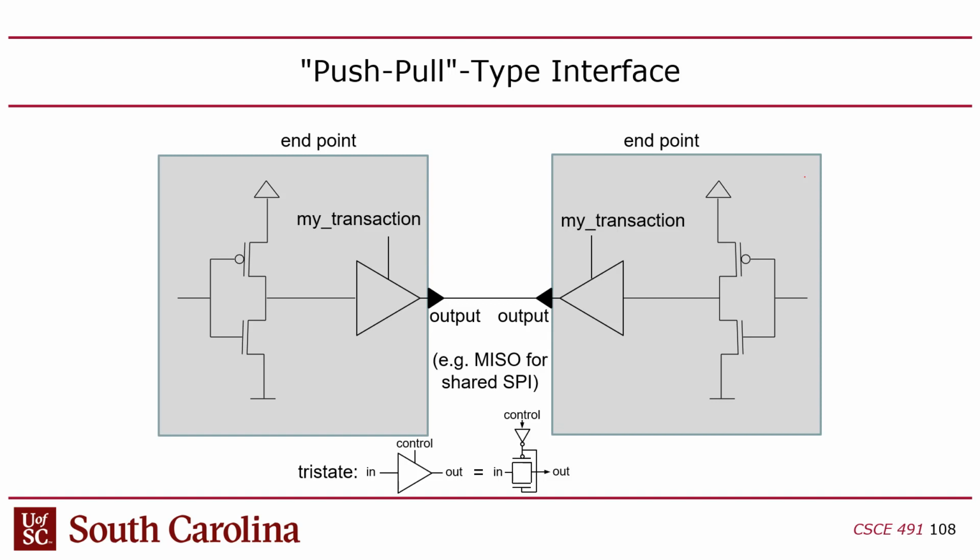So you could create a multi-SPI system if all of the SPI MISO connections had this tri-state capability. The problem is that it's expensive to do that. Plus, there's still no guarantee that the chips won't erroneously think they should both be talking, and they may turn on two tri-states, and then you still end up with a short, right? So it's not a great solution, right?